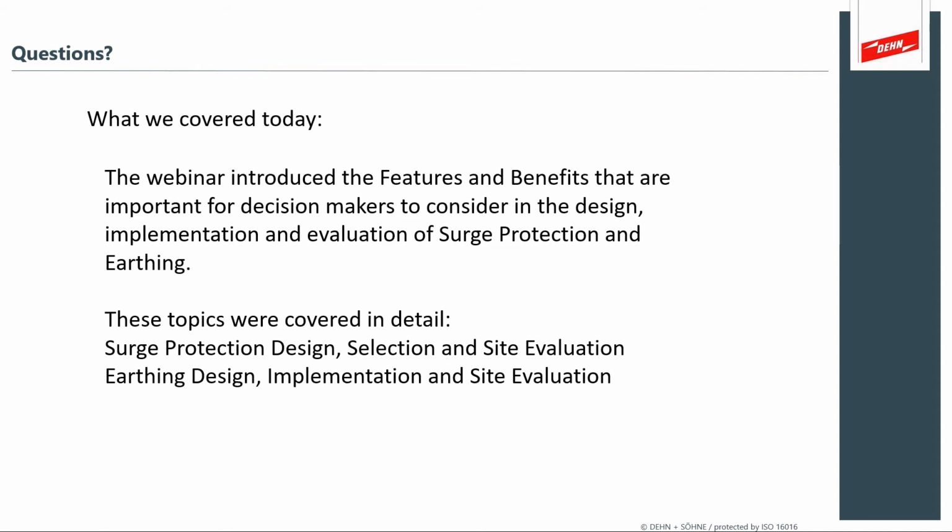And the thing is, there's two factors that really reduce when you select higher lightning protection levels, and that has directly to do with the current carrying capability of the surge protection device, as well as the voltage protection level. So you'll notice from our specification sheets that Mark showed that the nominal current that the SPD can handle is higher for a selection of LPL 1 or 2 than it is for an LPL 3 or 4, and that reduces the risk even further. So I just wanted to mention that as well.